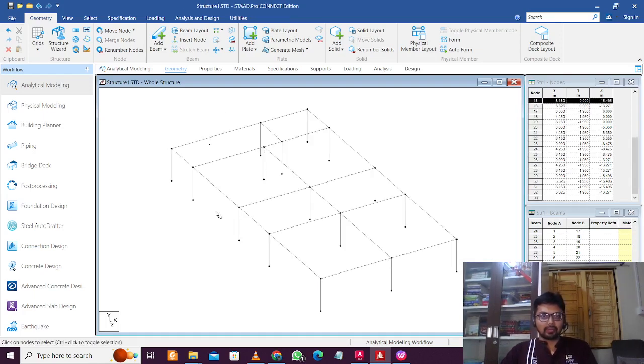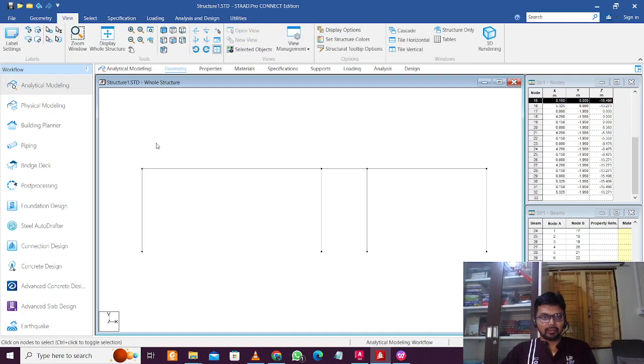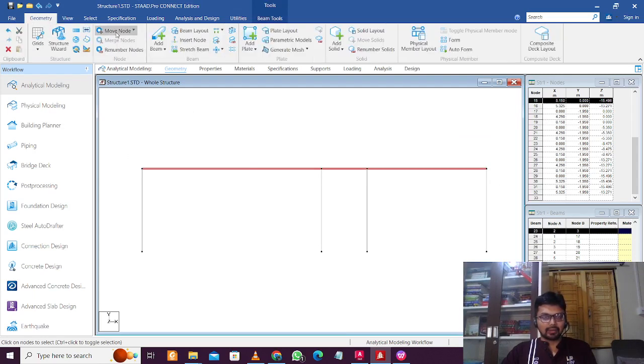So this is the base here. For the base, you can do this later. So we can go to view and select the front view. Make sure you have the beam cursor on, select this portion, and then we'll use translation repeat again, geometry. Okay, I think we have one place where we don't have any column, so I have to delete that.